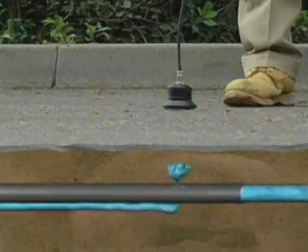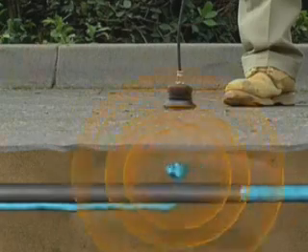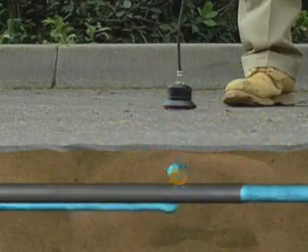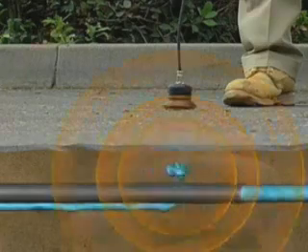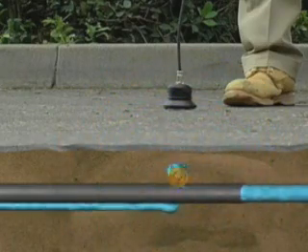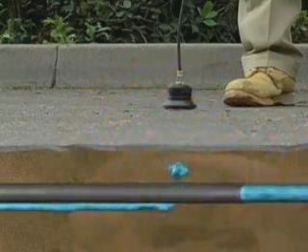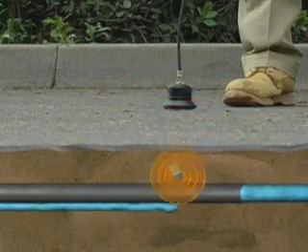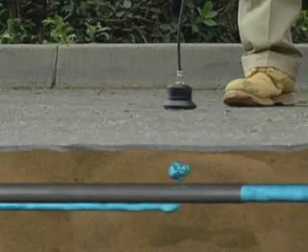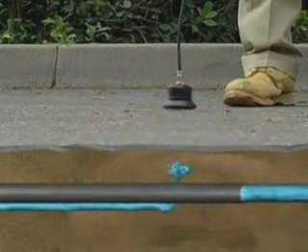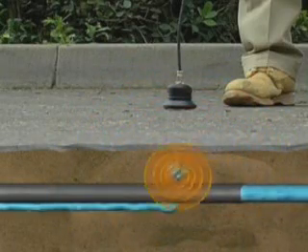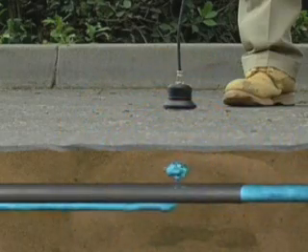Water forced through the crack and hitting the surrounding soil. This leak is quieter and is affected by the type of material around the pipe. If it's rock or gravel, a hammering or knocking sound may be heard. If it's loose soil, you may not hear anything at all. Water flowing through the soil cavity creates a gurgling sound, like a small stream or brook.